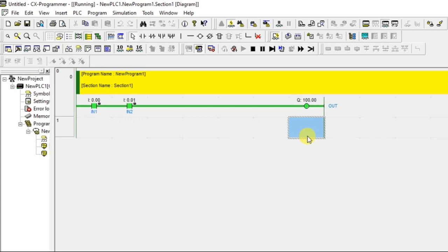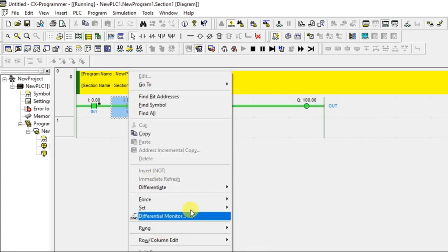While you are getting the result for the AND gate, you have to perform all 4 logic conditions in one concept. It's not that each condition has its own rung and its own line. There cannot be different logic for this. This is the only concept for the AND gate. So you have to put both the inputs in series to get the result. Understood? So let's turn off both.